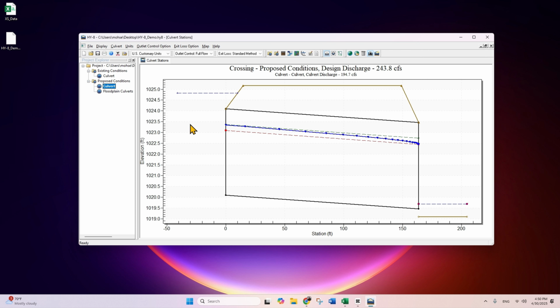So now this is essentially the design that we came up with. We just went back and forth, trial and error, changing some parameters. We wanted to see how it impacts the flow in our culvert. Now you can see in our big 4 feet diameter culverts, the barrels are not full for our design flow, and it's running partially full right over here.